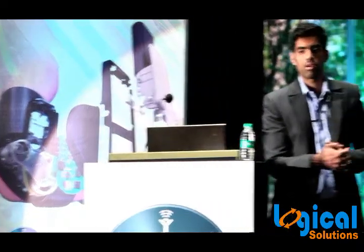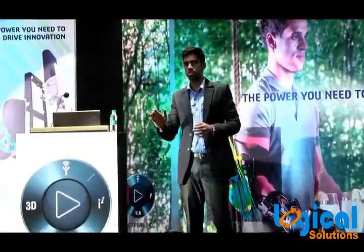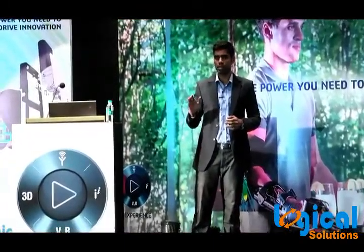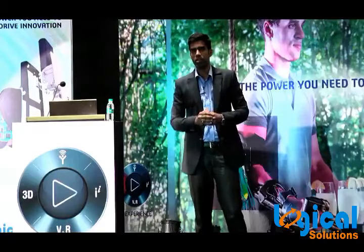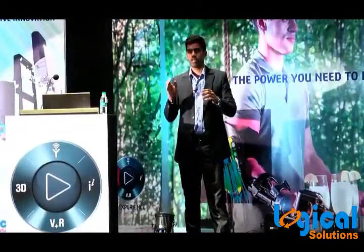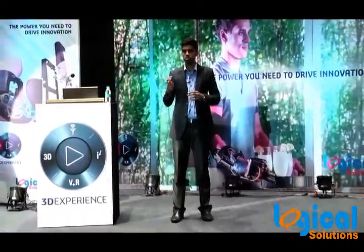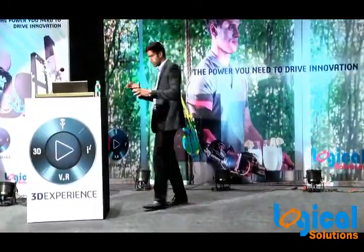What about configuration? Have you ever used configuration? What is a configuration? Configuration allows you to represent more than one version of a part or assembly in the same file, right? So if you have a part with different sizes, you can create a configuration, save the different sizes, and use whichever size you want. You can switch between those configurations.